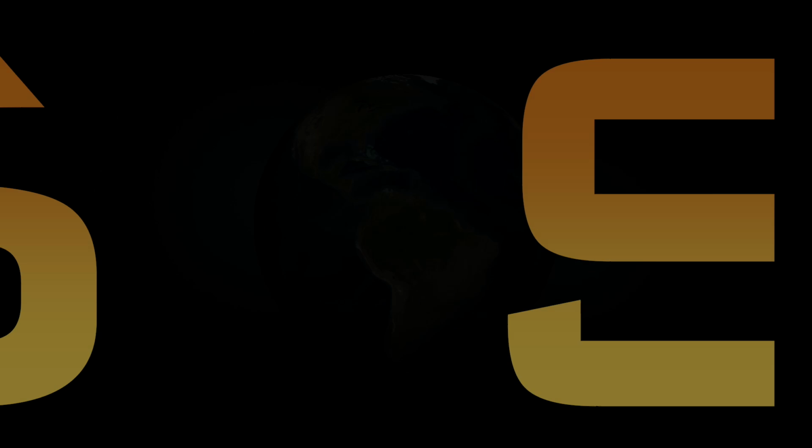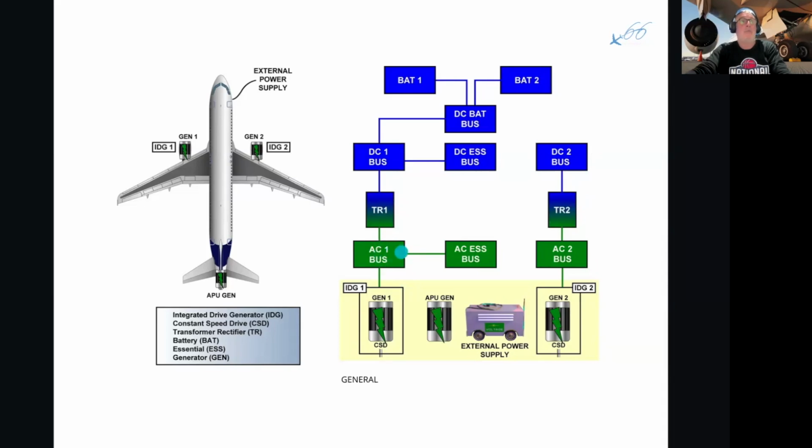Now, AC bus 1 automatically, in normal circumstances, if power was lost, will feed the AC essential bus. Similarly, DC bus 1 will feed the DC essential bus in an emergency.